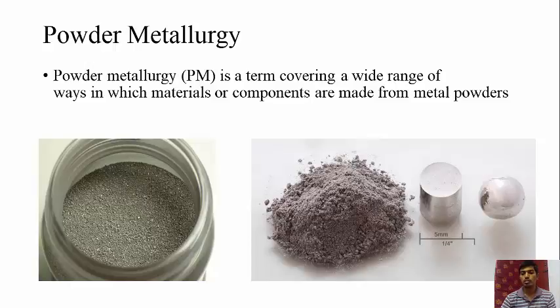After it is made into billet shape, it is heated to a particular sintering temperature according to the properties of the individual metals. After sintering is done, this material is again tested for mechanical properties. While testing, we can find that the mechanical properties obtained by the final metal are a combination of the material properties of metals A and B, which were taken as the starting material powders.